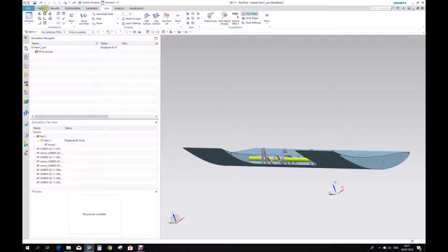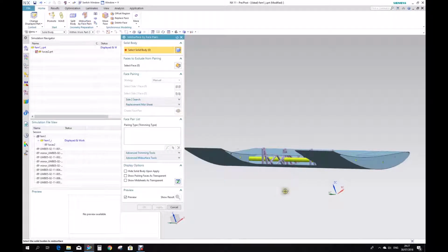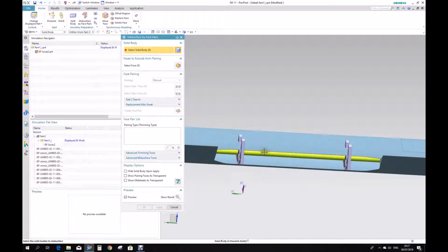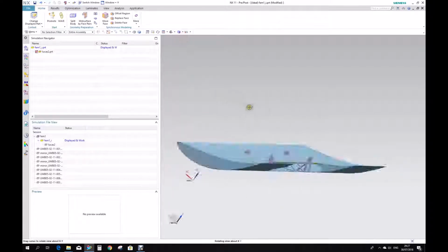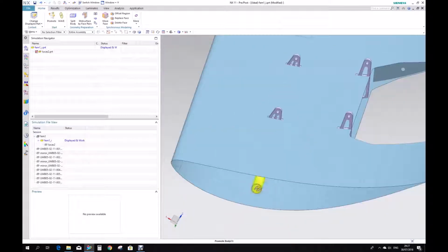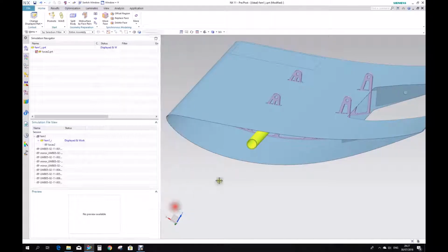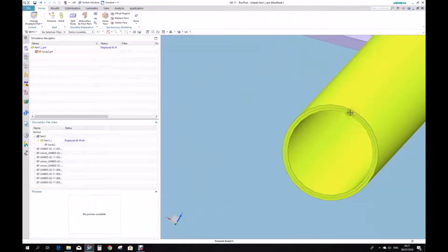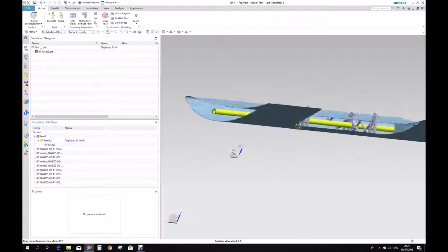So again, go in mid surface by pairs, then select the inside face and the outer side face. So what I'm gonna do first is hide this, so then I'm able to access the interior. So mid surface by pairs, this is our body, the first face, the second face, and apply. You can see that's there, the line representing the mid surface. And what else? Yeah, that's it.